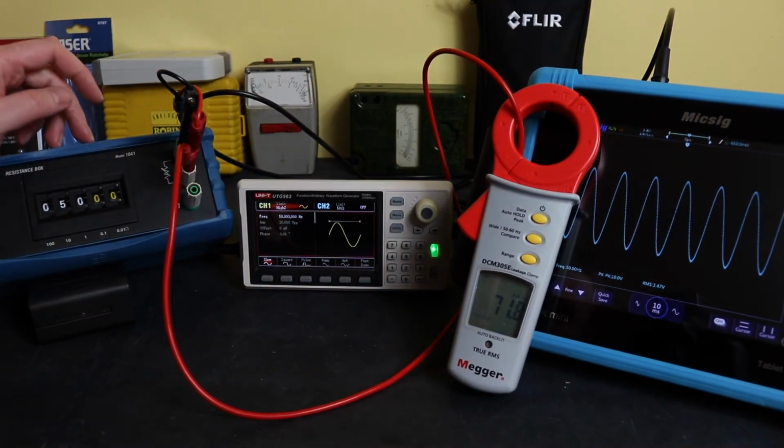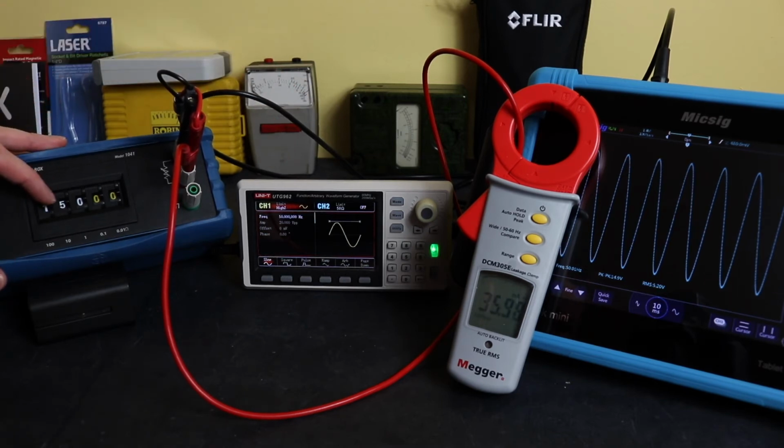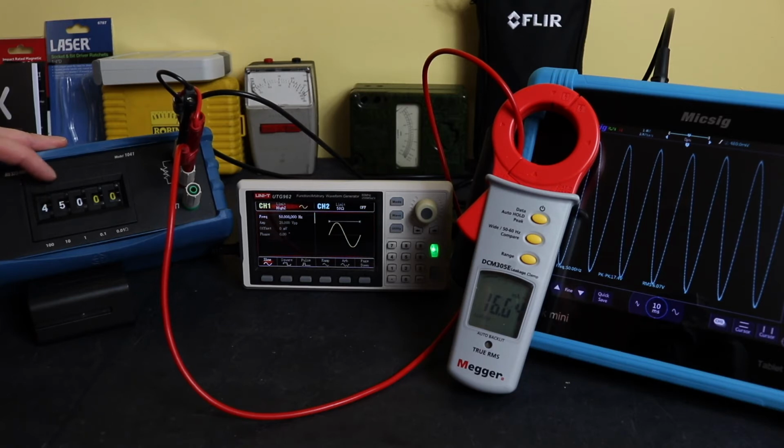Now, if I change the load that I'm putting in to simulate a high impedance, we'll put it up to 150 ohms, and you can see I've actually jumped up to 15 volts peak to peak there. Let's go to 250 ohms, and we got up to 16.5. But unfortunately, you see that my current is dropping. It's now dropped to 24 milliamps. Let's go up to 17. That's 18 milliamps, and that's 450. Let's go 500. But it's going down all the time.